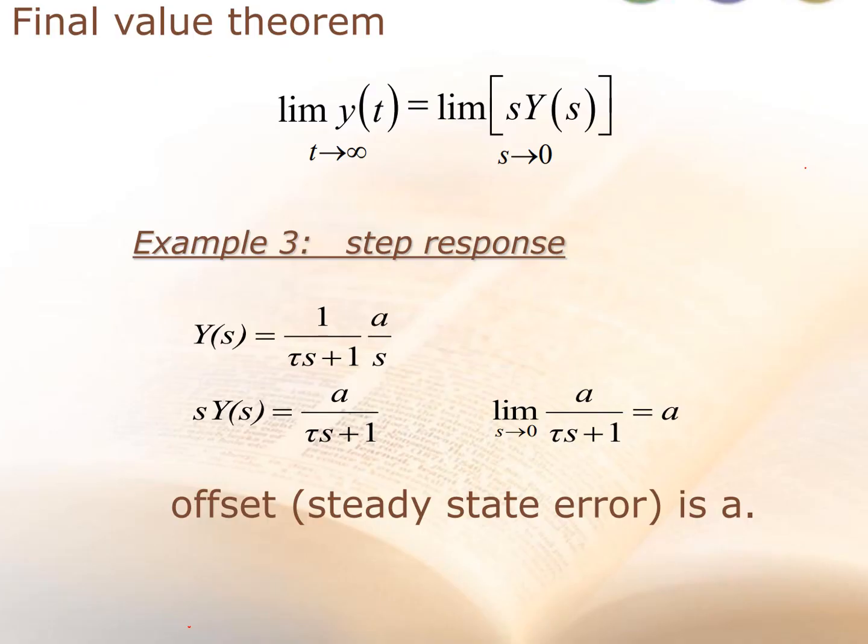So finally, what I want to cover is the final value theorem. When you take a look at a higher order transfer function, it is very difficult to do the inverse Laplace. One way to solve the higher order is to first reduce it to first or second order, either using the Taylor, Skogestad half rule, or Padé approximation.